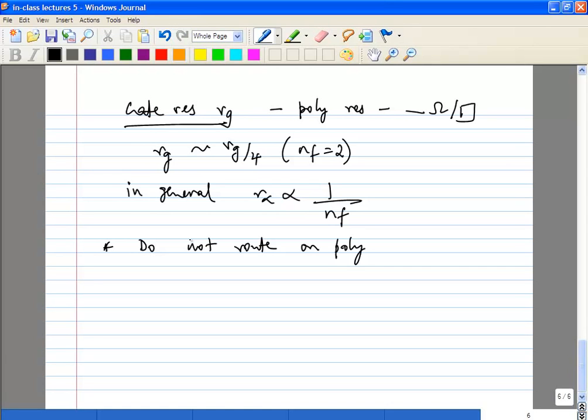There are certain cases where people do poly connections, and those are done for standard cell gates. You will see standard cell gates where, for example, somebody is building an ASIC and wants to do an auto place and route involving millions of gates, which means each gate should be laid out as efficiently as possible.